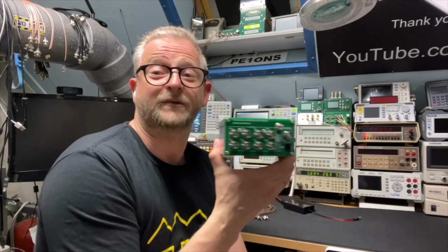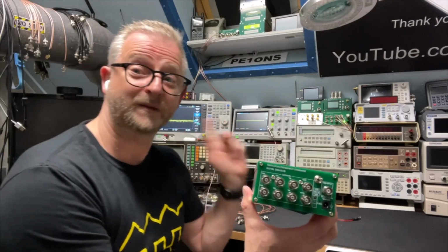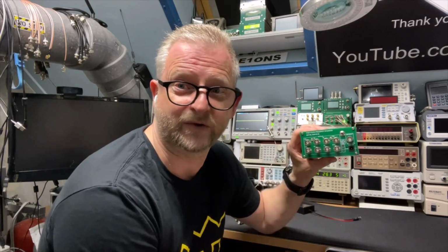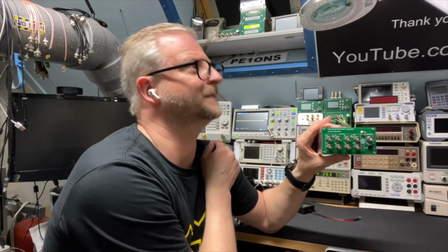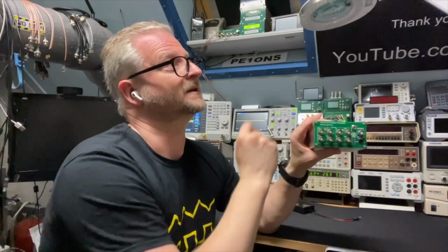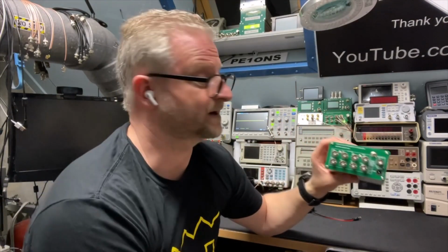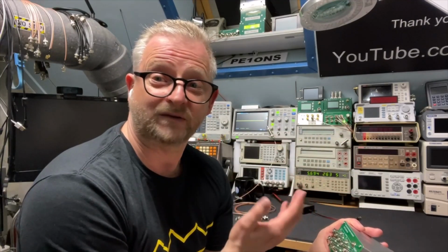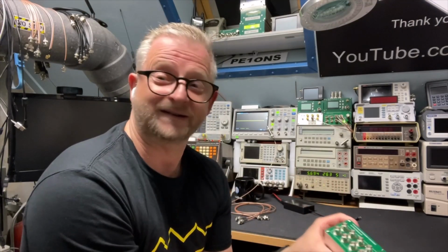And this is great if you have older equipment. I have here my Marconi that runs on 1 megahertz external reference. You need to think usually when it's 1 megahertz, it is high impedance, like 1 mega ohm or something, so you need to put also a terminator resistor on your BNC. And I have there also an older Nixie frequency counter from Marconi. That one also runs on 1 megahertz, so that's why I needed this one. But some older HP equipment, I think also runs on 1 or 2 or 5 and something. So that's why you need that.